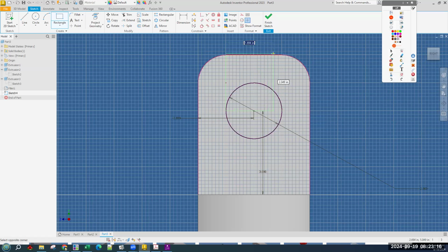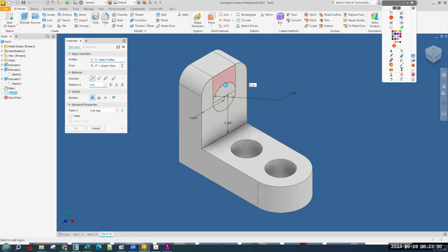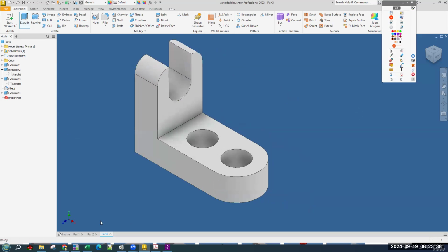And the other one needs to be at the top edge, lining up exactly with the other. You'll get a snap here where the fillet ended. That's convenient. Then we finish the sketch and extrude all of the things that we drew. Switch it to cut through all. And there you go. This is part 13.